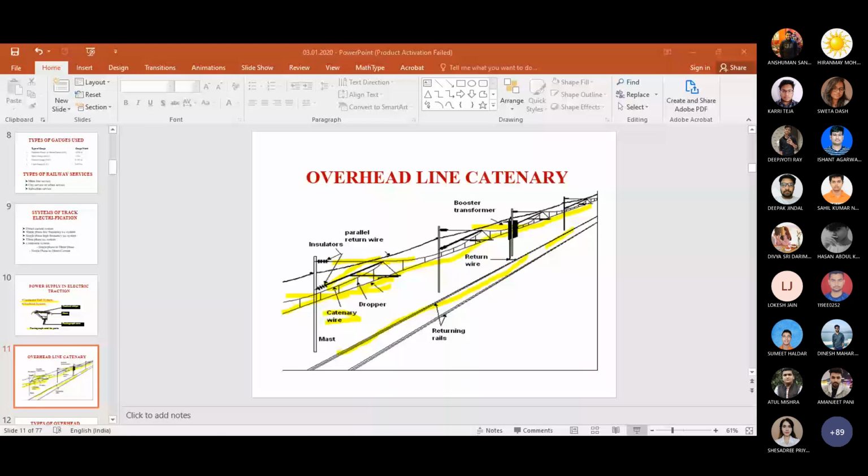Initially, based on the current rating, here you can see some contact wires and the rheostat grids. As per your demand, you can connect the contact wire and control the speed of that motor below base speed. Up to base speed it is allowed. After that, you need to follow another method. Here you can see the rheostat grid and its contact wire.